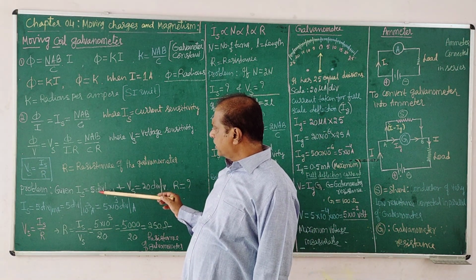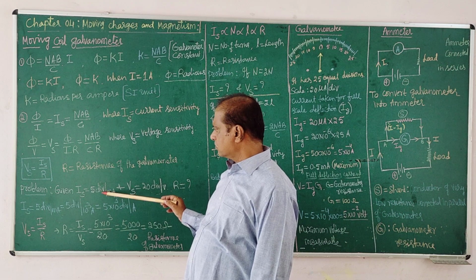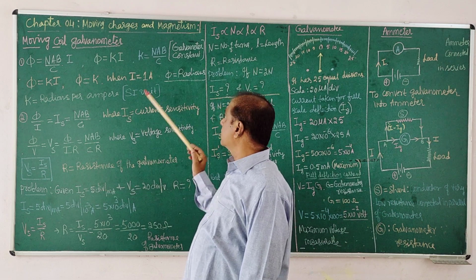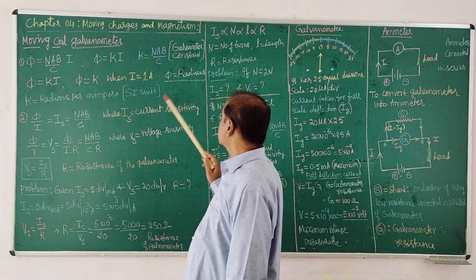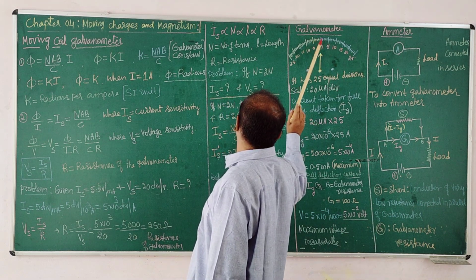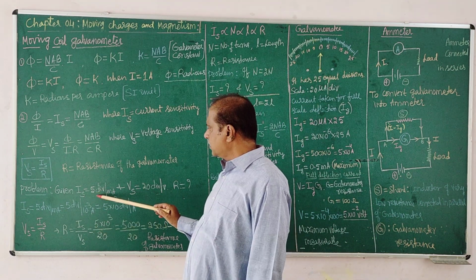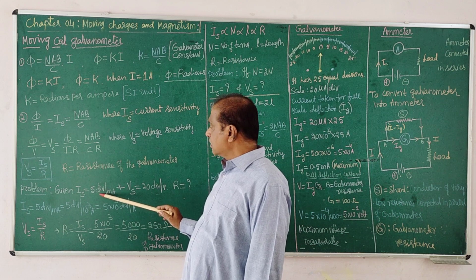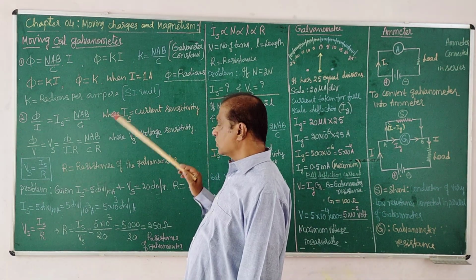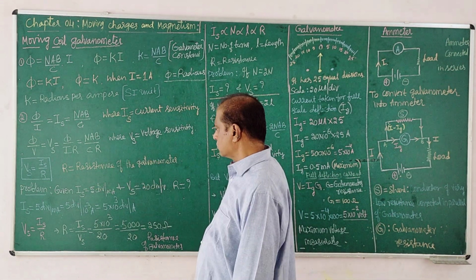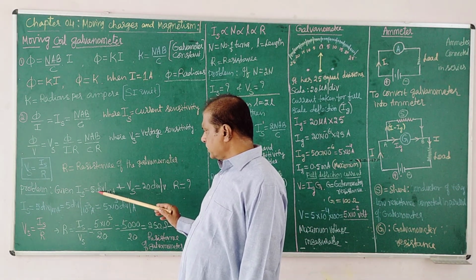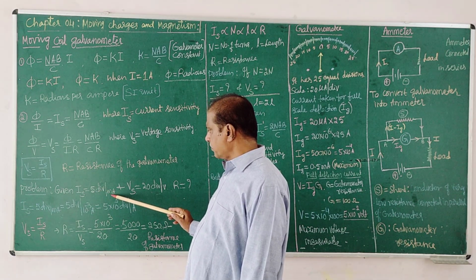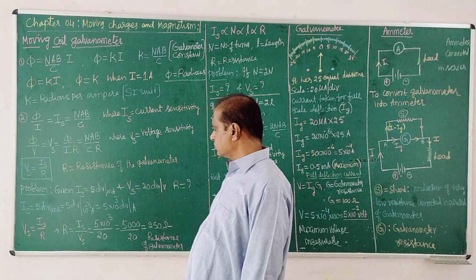So now it is not in radians. We can represent the radians in the form of number of divisions, because of the angular shape. These divisions on the angular scale are almost directly proportional to the radians. So it is represented as 5 divisions per milliampere current sensitivity.